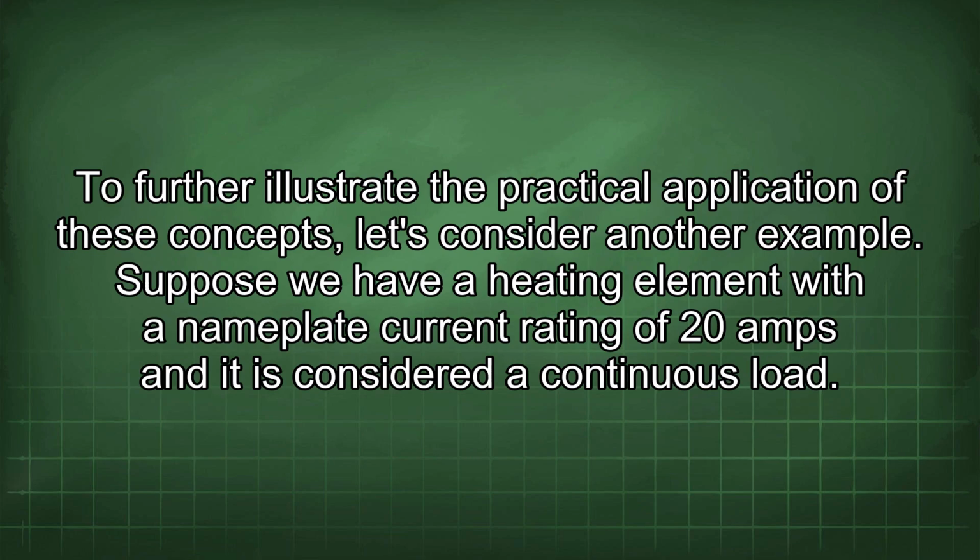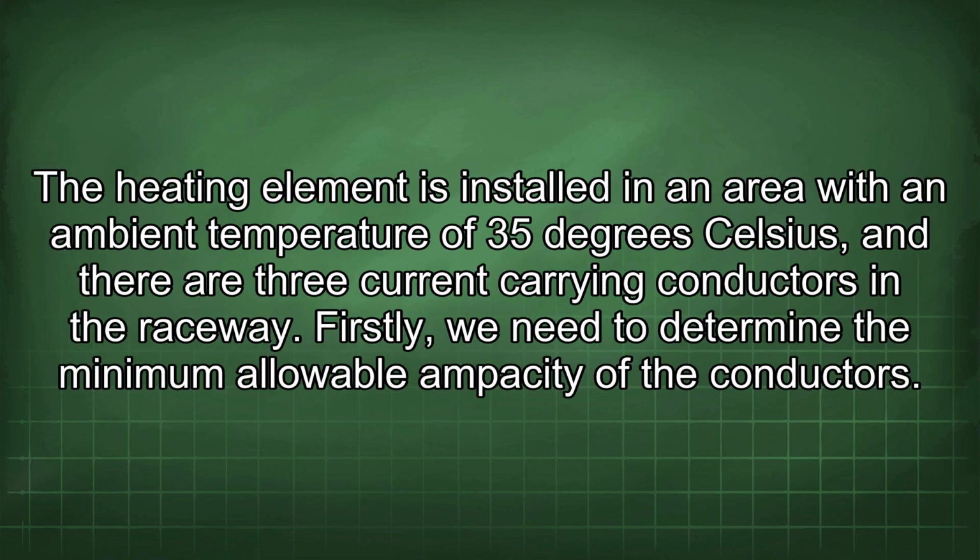To further illustrate the practical application of these concepts, let's consider another example. Suppose we have a heating element with a nameplate current rating of 20 amps and it is considered a continuous load. The heating element is installed in an area with an ambient temperature of 35 degrees Celsius, and there are 3 current-carrying conductors in the raceway.